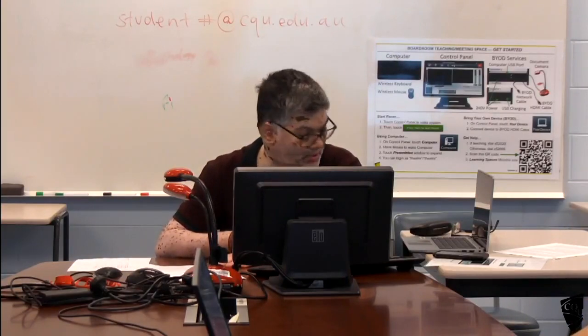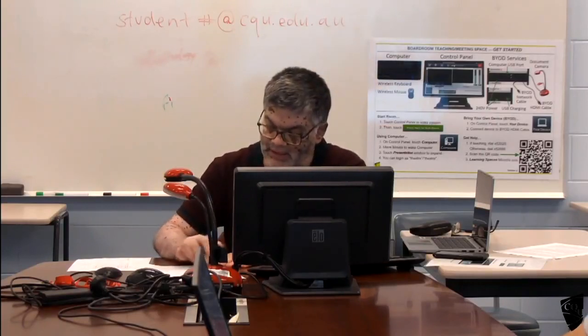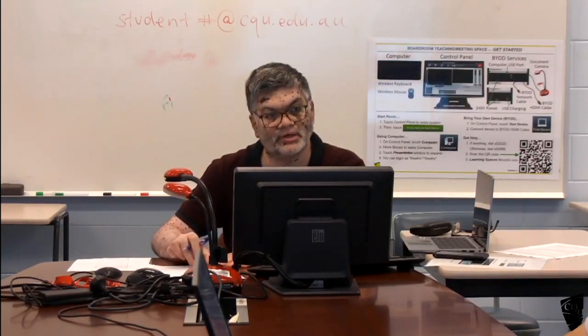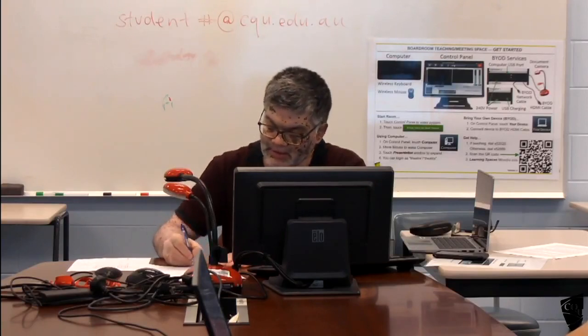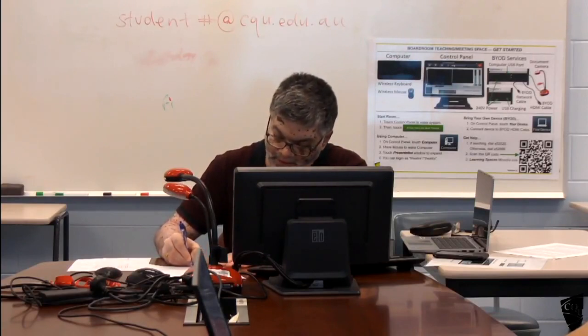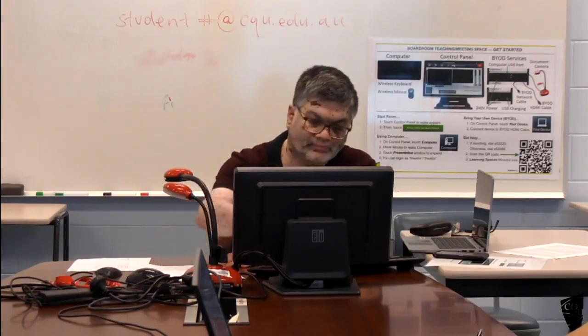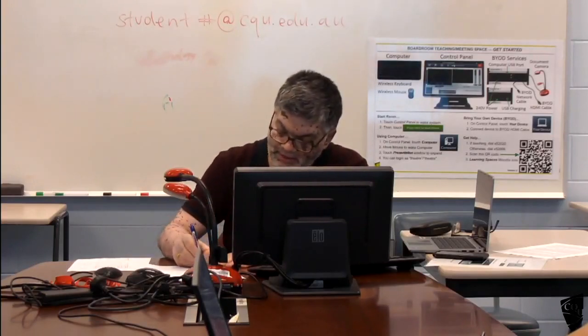The last column is interior negative moment 0.75. So interior for this end span, this is the interior, this is exterior. Okay, I'm talking about end span, exterior, interior. So this factor is 0.75 MO1. For positive, they said 0.5.